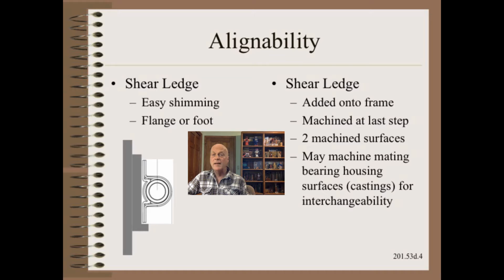Many rollers may need alignment and periodic realignment. While in principle any roller can be aligned, in practice some mounting styles are far easier than others. For example, the shear ledge shown here is as easy as it gets, while most bolt-bound dual plate designs are next to impossible to align. The shear ledge allows the crew to level first by shimming. Then they can square the roller as a second step without losing level because the ledge supports it.